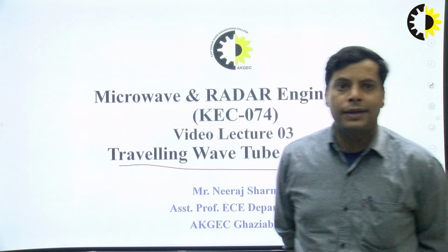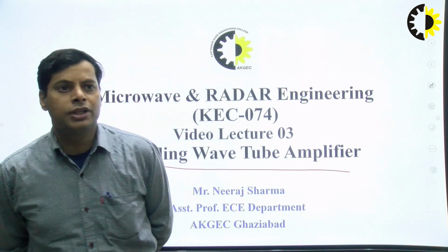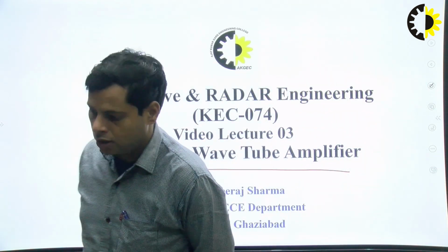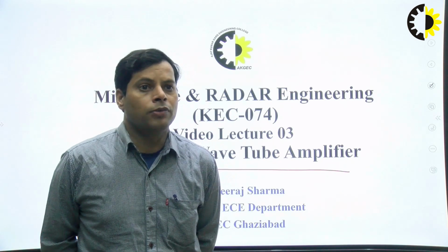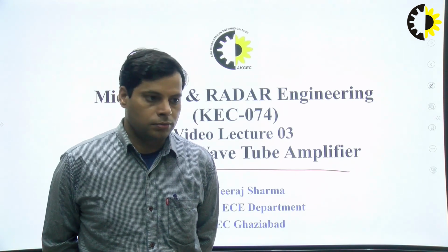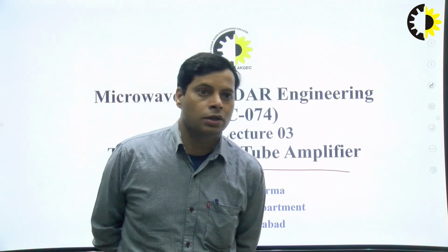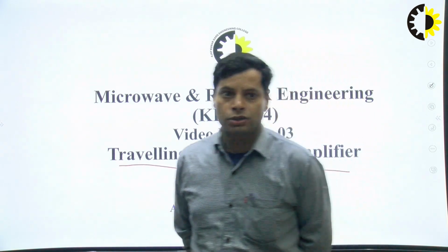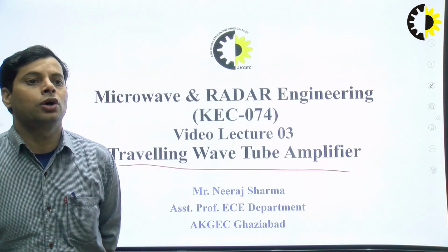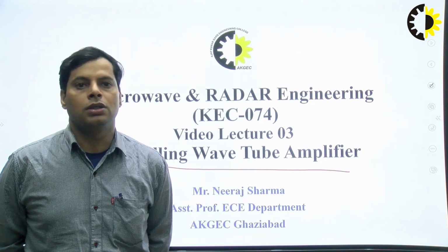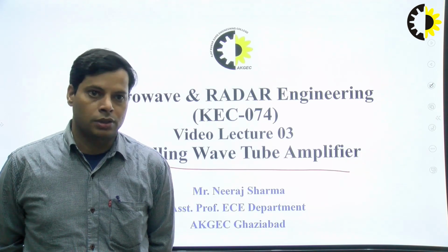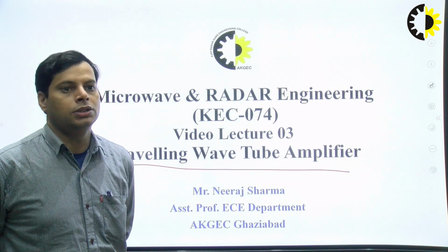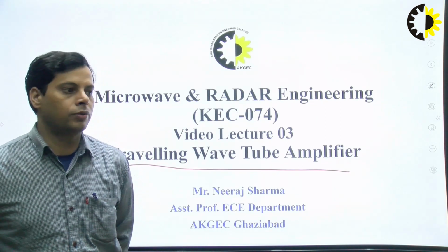Electrons coming from the electron gun and crossing the gap between the cavity interact with the RF field, and after this interaction, velocity modulation is generated in the klystron tube. Velocity modulation is responsible for the bunching of electrons, and after that the electrons amplify the RF signal. So the main concept is that the cavity gap is responsible for the generation or the amplification of the microwave signal.